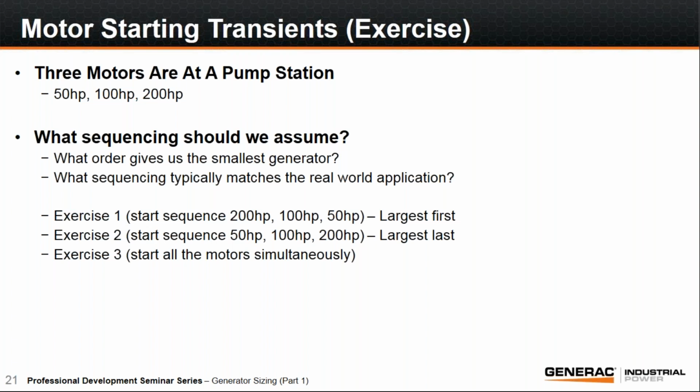And very rarely do you shut everything off to restart the big motor. You keep the things running that are running, and when the big motor kicks back in, it starts last. So keep that in mind.